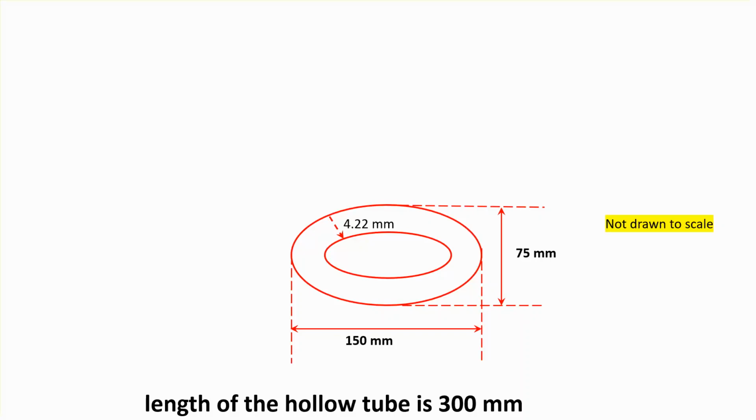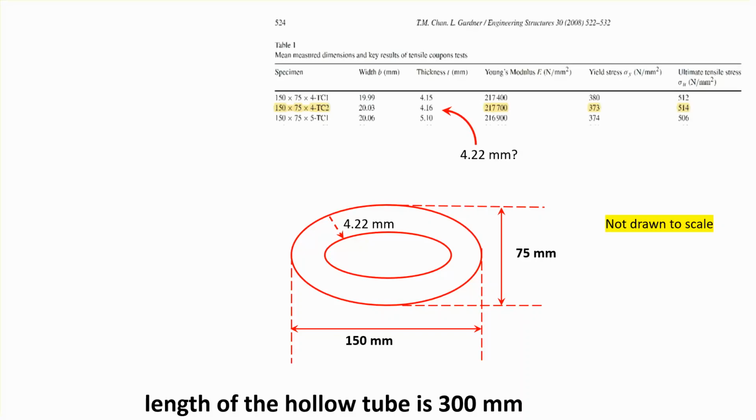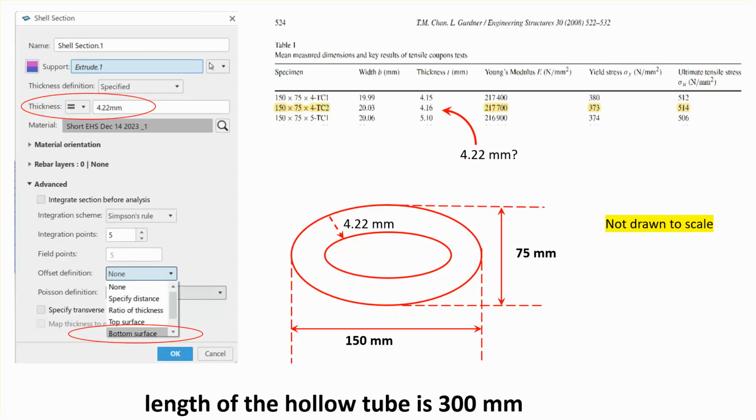The surface that I will draw is going to be the outside surface. That's basically the negative side of the shell elements, and then I'm going to extrude them inwards by the given dimension. This data is coming from a paper that's way up there, and we are doing the middle row of this. Now, as I mentioned, the surface that I generate in the 3D Experience is actually the bottom surface. That's why when it's extruded, the shell goes by that different distance of 4.22 millimeter inward.